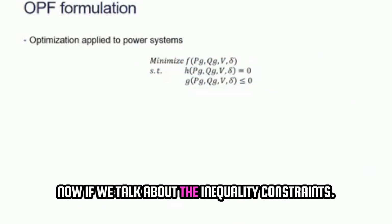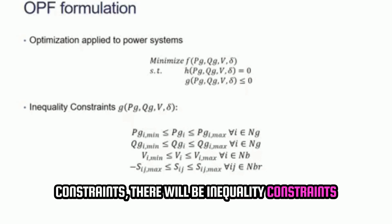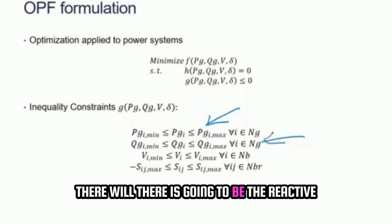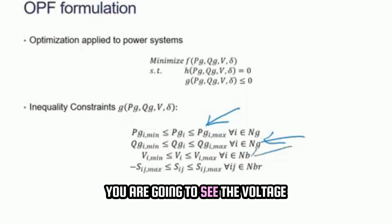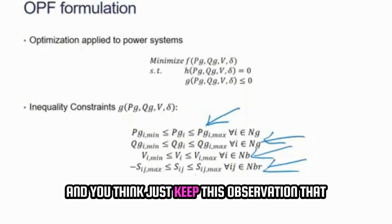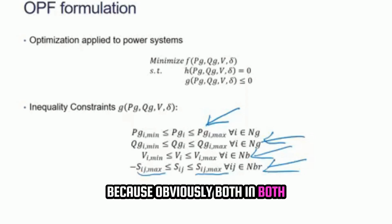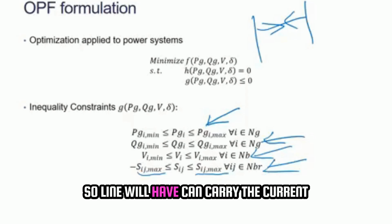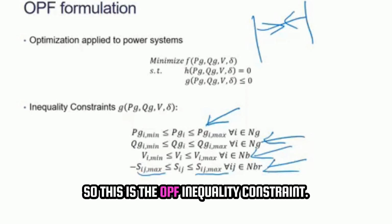Now if we talk about the inequality constraints, there will be inequality constraints corresponding to the real power generator, its maximum limit, minimum limit. There is going to be the reactive power generation limit, QG max and QG min. You are going to see the voltage max and voltage min limits, and the line limits. Keep this observation that Sij max is there, only I'm adding a minus sign because obviously in both the directions the power flow is going to be the same, meaning the maximum it can take. So the line can carry the current of the same capacity in both the directions, right? So this is the OPF inequality constraint.